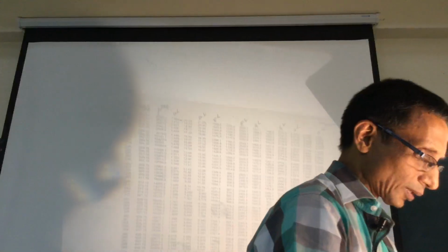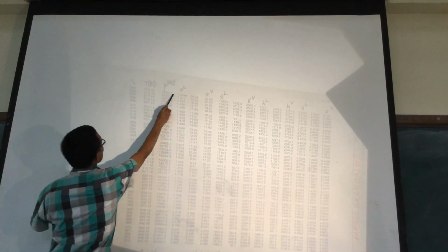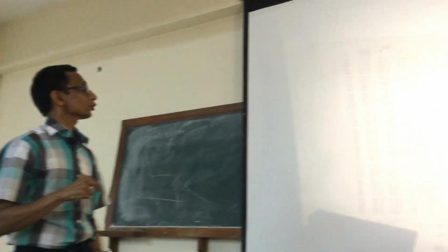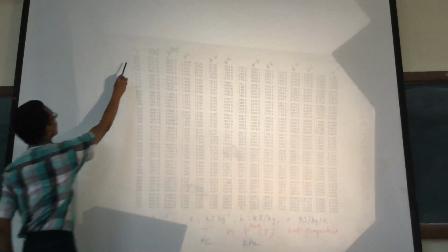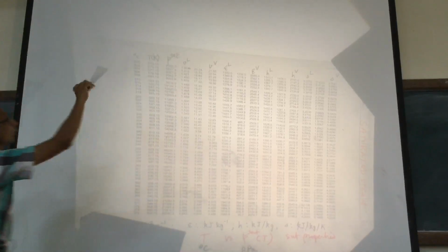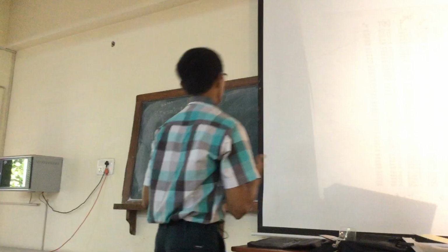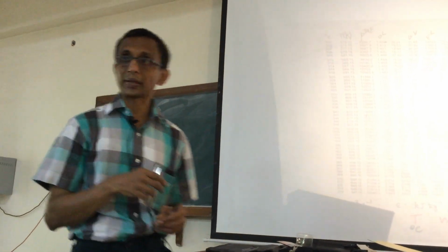If we move this a little bit, now maybe you can see here. The saturation pressure is in kilopascal, 8592.7. I hope at least some of you can read. This is the 300 degrees centigrade given in Kelvin, and you have all the properties, the volumes of the vapor and liquid saturated. So this is purely saturated. Enthalpy, everything you get. So now 8592 kPa is 8.6 megapascal.